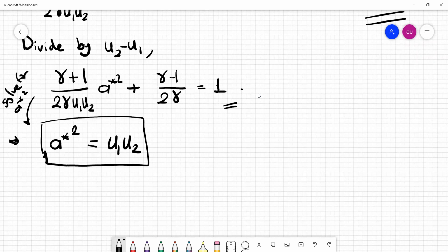Well, in compressible aerodynamics, this relation is known as the Prandtl relation. Okay, and it is basically the backbone of normal shock wave relations, relating state 1 before the shock wave to state 2 after the shock wave. It is the backbone of this analysis, equation 10 here. Why?